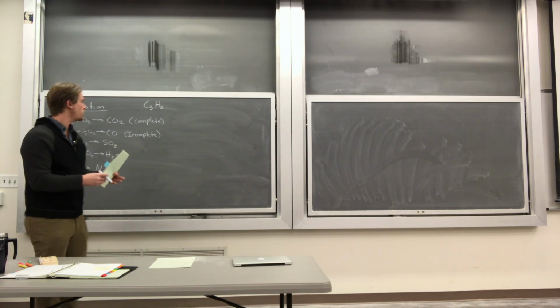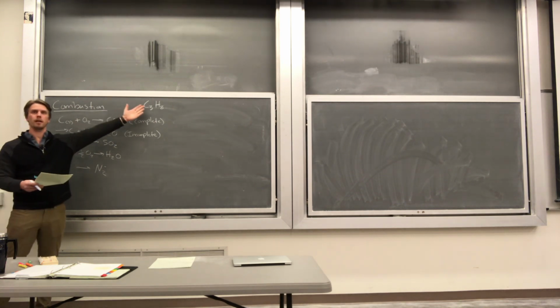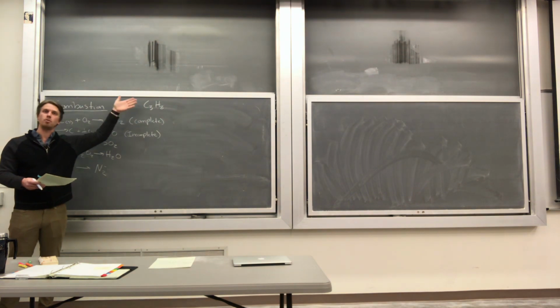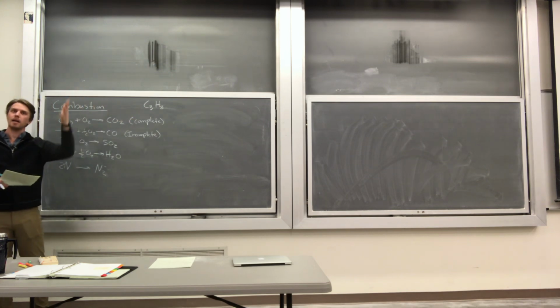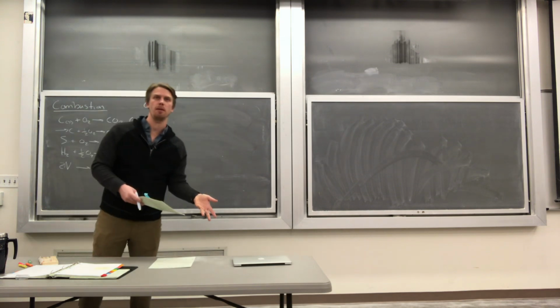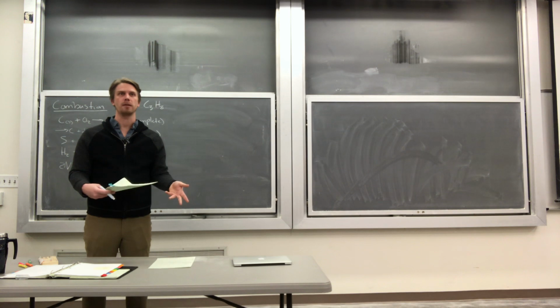Okay, so this is the only new complication with combustion, and we've got a couple of other definitions, but basically when you see a compound like this, we can explode it into atoms. Oftentimes when we're burning a fuel, we do not know it's propane. We don't know it's ethane. It's just some fuel that we happen to purchase. And we may have an atom composition, and we have to be comfortable converting between a mass percent basis and a mole percent basis, right? Because moles react, masses don't.